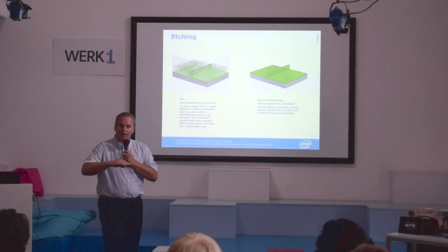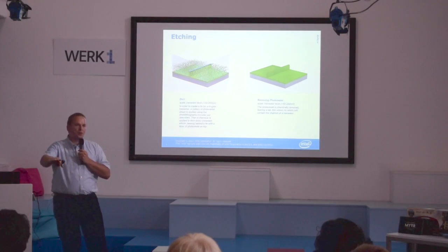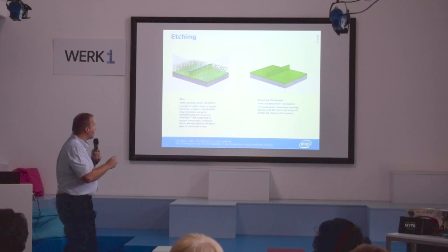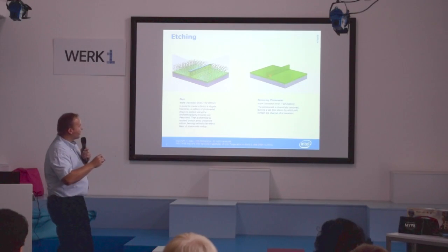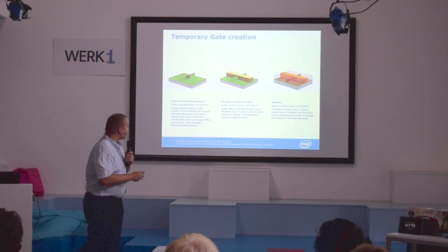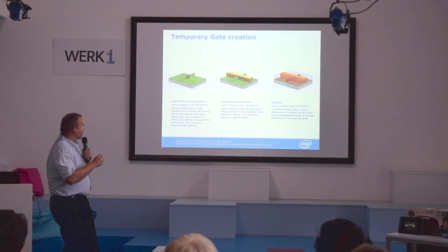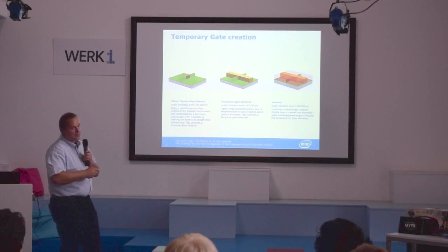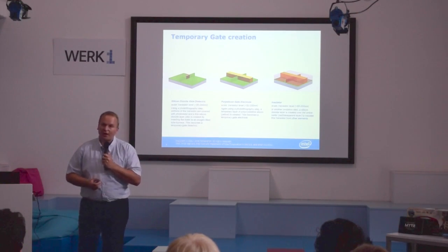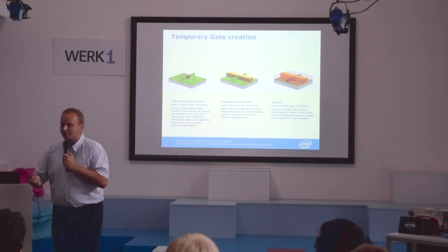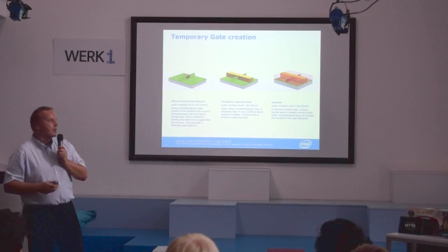So it's not just on the surface of the wafer. We're actually, by etching away parts, creating fins. And then when we remove the photoresist, there's another step where we would plant the silicon dioxide gate dielectric, which is the heart of the transistor. That actually makes the transistor switch or not switch.